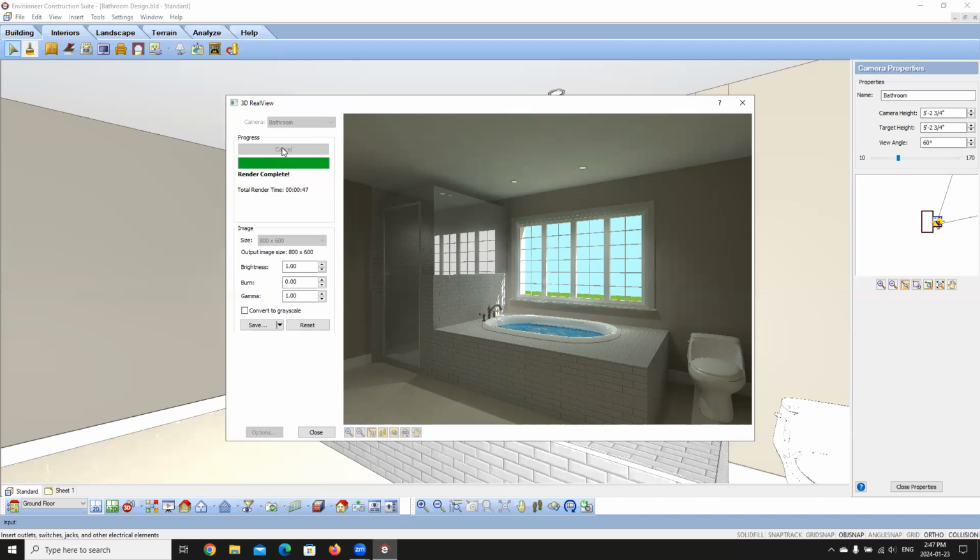You can also use the Walls tool to create a custom tub enclosure. And then you can use the Surfaces tool to create a custom platform top for it. After inserting the tub into the platform, you can use the cut opening tool to cut a hole through the top of the surface to show where the tub is going to be. And then we also looked at how to use that surface tool to create custom elements like water to help give your renderings a little bit more realism.